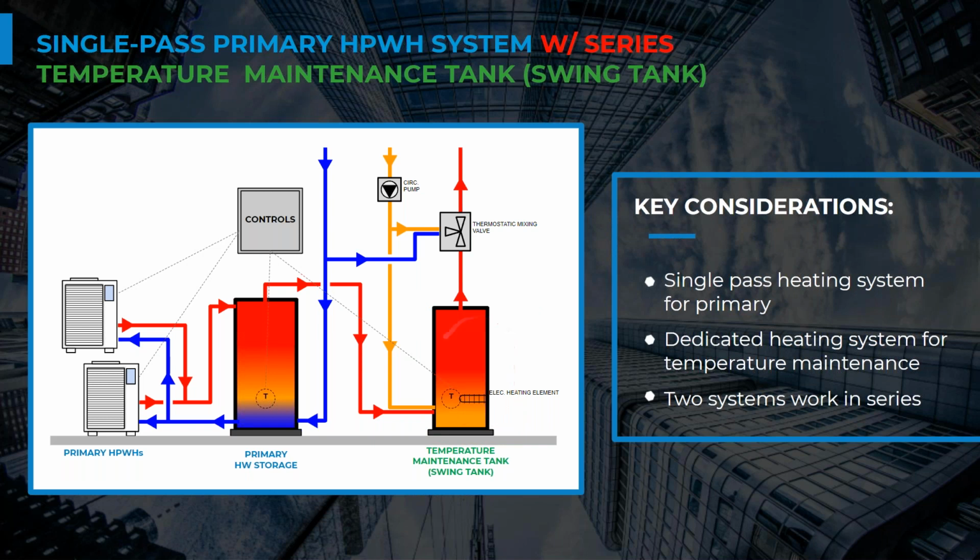And so if we get a lot of swing in our tank and it drops below 125, that's when our electric resistance element will come on and heat that water up inefficiently. So we want to design for that not to happen. And that's why we need a large volume there, so that we can match that volume with essentially a longer duration of low use overnight.